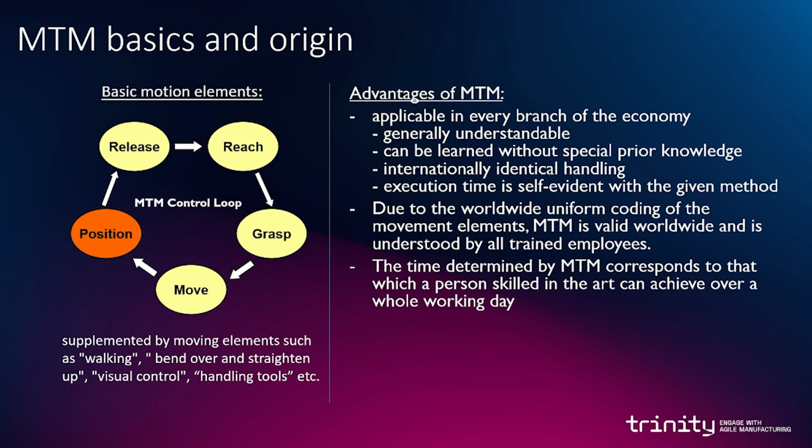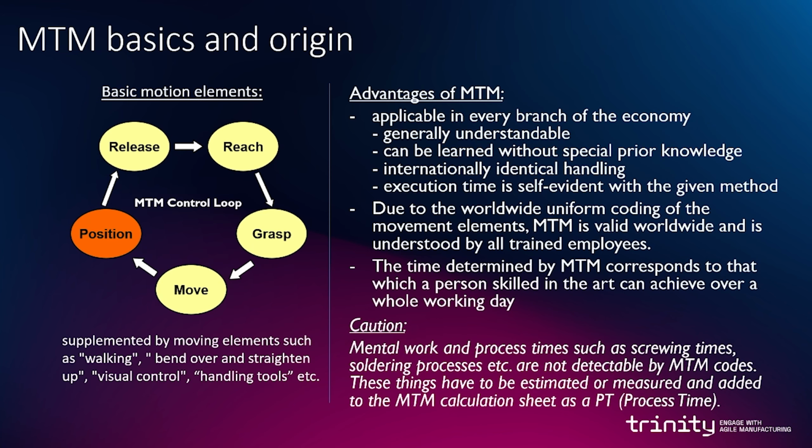But what we have to consider is that mental work or process times, such as screwing times or soldering processes and so on, are not deducible by MTM codes. These things have to be estimated or measured and added to the MTM calculation sheet as a process time.